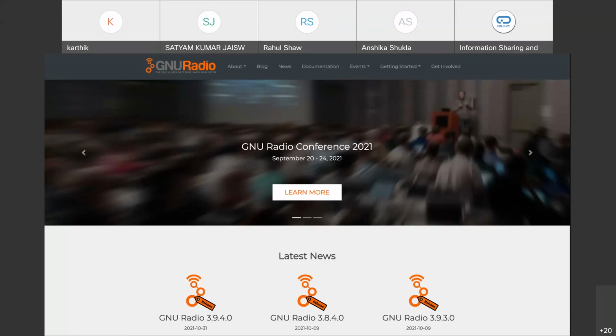So you can connect that equipment and, as I said, decode the data and apply various sorts of algorithms, tweak the signal, and do a lot of work with whatever radio signals you can find. You can also use GNU Radio to scan all the signals, latch on to a particular frequency, and then whatever data is incoming in that frequency, you will be able to decode it. At the same time, if your SDR supports it, you can also use this to transmit data.